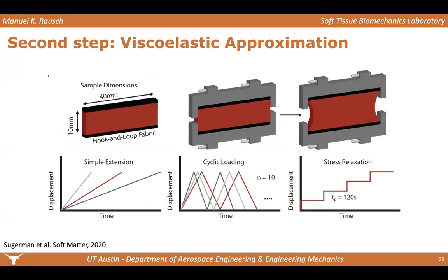So now that we have a very fundamental understanding of blood clots, we know it's strain stiffening, we know it undergoes a negative Poynting effect. We've identified a hyperelastic material model to capture the elastic effects. We wanted to start looking at a mode of deformation under which we could study fracture. And so if you look at classic fracture experiments, a mode 1 experiment, you see these geometries that people refer to as pure shear experiments, right?